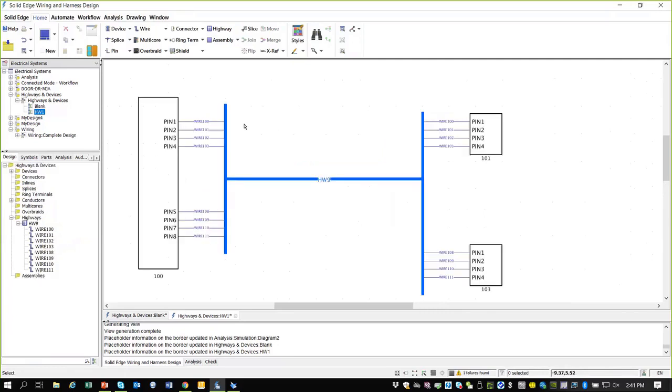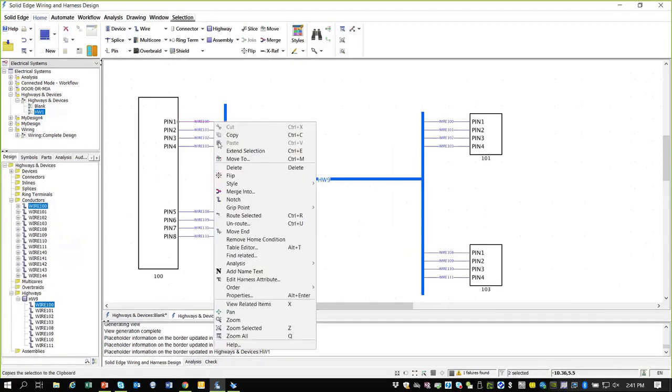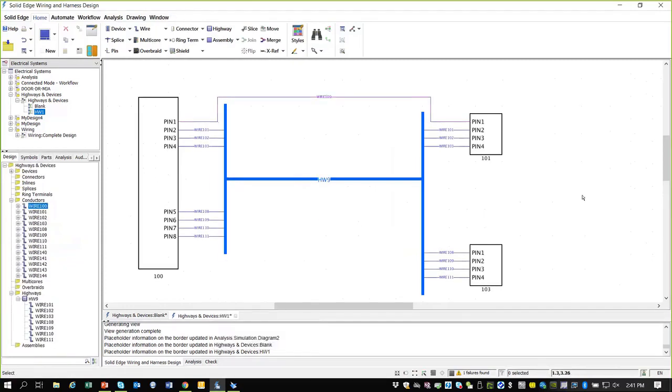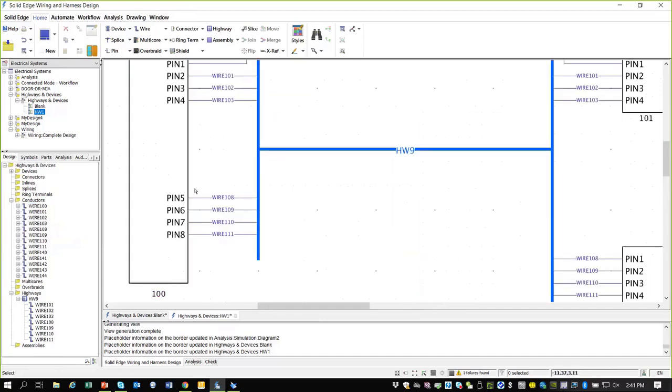You also might want to do, this would be pretty common, it's like, hey, this wire 100, I really like to unroute that and pull that out. If that's kind of a control or special wire, it's easy to read, so people can follow, okay, I can see that's the control line for this bus of wires that's going through there. So we can do that. We can even do stacked pins on the fly here.